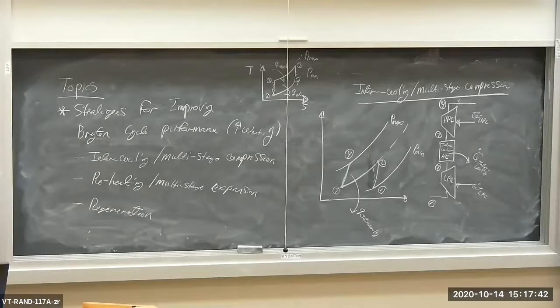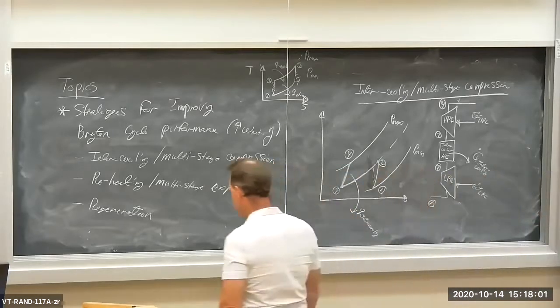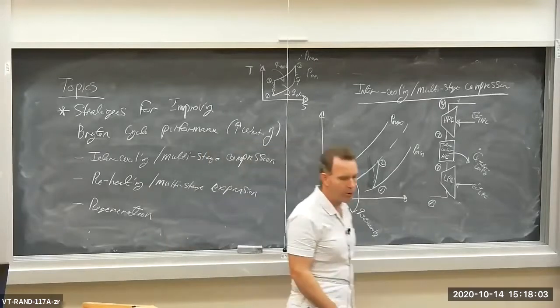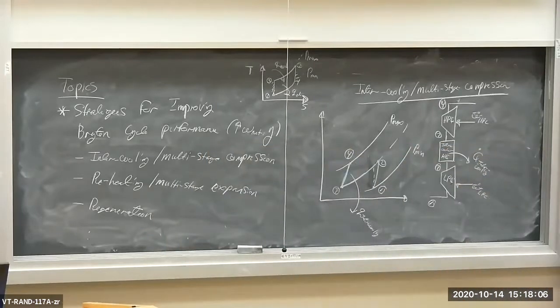Now, once the air gets compressed in the turbocharger, it gets cooled down by a heat exchanger placed in front of the radiator on your car, and that heat exchanger is called an intercooler. So if you've got a turbocharged car, whether it's a diesel or a gasoline, it may say somewhere, either in the owner's manual or maybe even on an emblem or a label on the car itself, intercooling or turbocharge with intercooling.